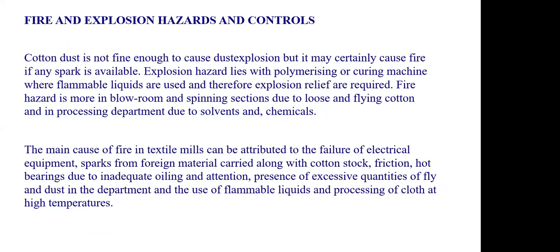Fire and explosion hazards and also the control measures. Apart from this, with respect to machineries, we have fire and explosion hazards in this textile industry. So the cotton dust is not fine enough to cause any dust explosion, but it may certainly cause fire if any spark is available. So the cotton dust itself is not going to cause it, but there are chances this happens in case of any spark available.